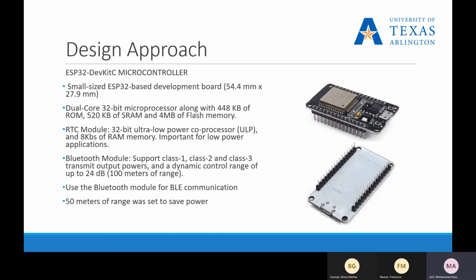The ESP32 Dev Kit C module, which we are going to be using, comes with an entire small size system on chip, which in terms of current and voltage seamlessly integrates with our motor and battery choice. This was an important constraint that needed to be considered in our design, as not a lot of space is available behind the bottom louver where this is going to be installed. Most of the I/O pins are broken out to the pin headers on both sides for easy interfacing. It is possible to connect peripherals with jumper wires or even mount the whole chip on a breadboard.